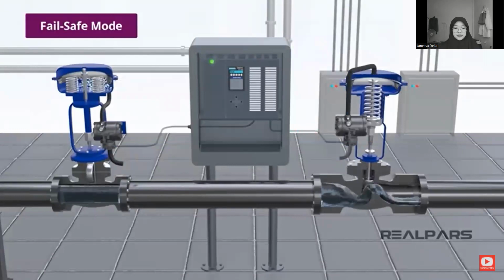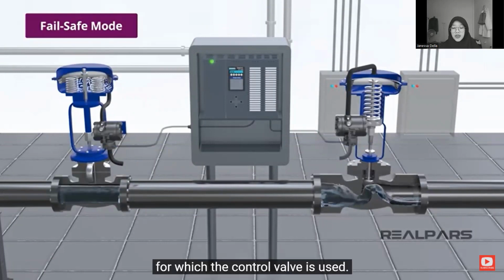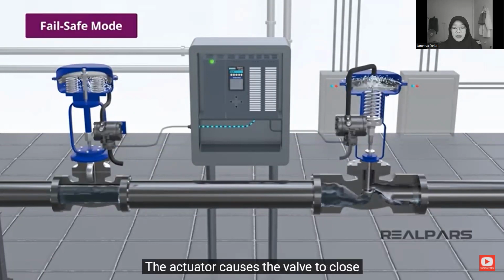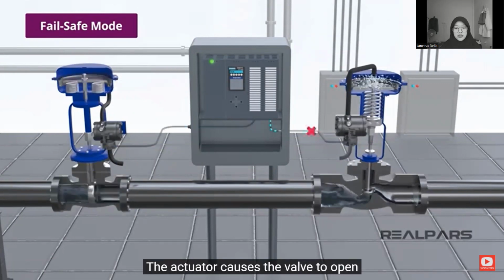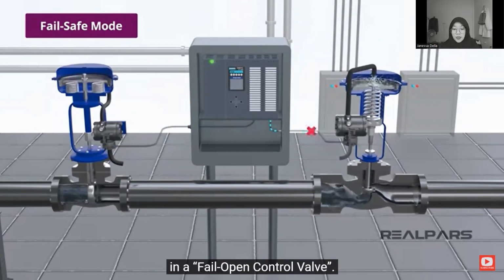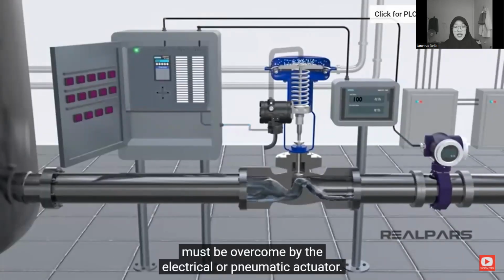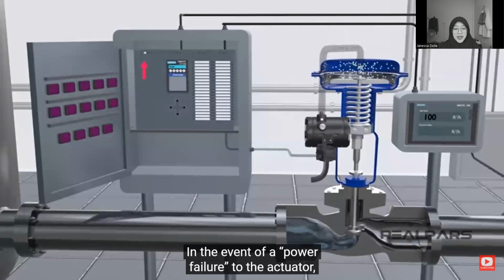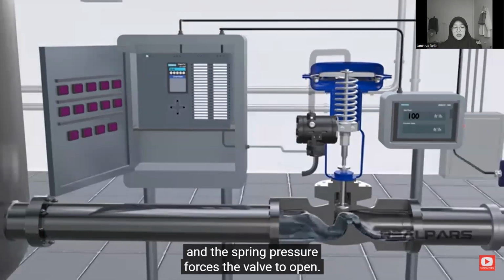fail-safe mode. The type of fail-safe mode depends on the application for which the control valve is used. The actuator causes the valve to close in a fail-closed control valve. The actuator causes the valve to open in a fail-open control valve. In normal operation, the force of the spring must be overcome by the electrical or pneumatic actuator. In the event of a power failure, the actuator or pneumatic force is no longer present, and the spring pressure forces the valve to open.